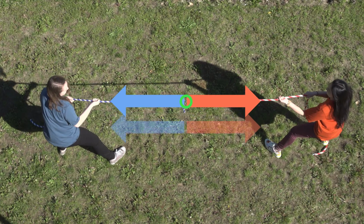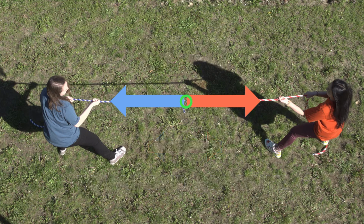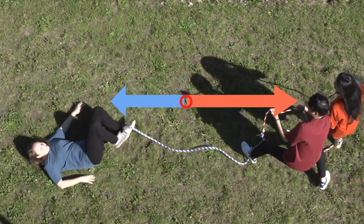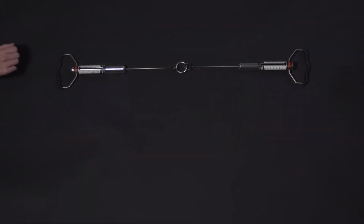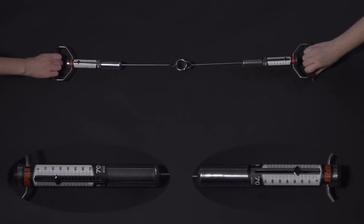For equilibrium to exist, the two forces on the ring must be equal and opposite. Or, as an engineer might say, the vector sum of the forces on the ring must equal 0. If the forces on the ring do not balance, then the ring will move. We can quantify the forces involved in the tug of war by using spring scales, and in doing so verify that the forces are equal and opposite.